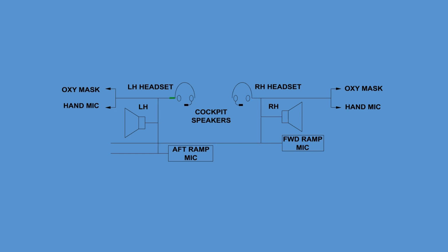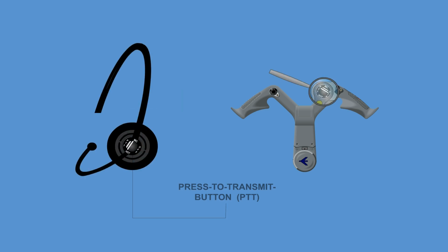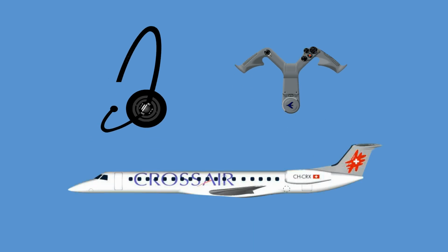The digital audio panel supplies two-way interface between audio signals from cockpit or ground stations or via interphone link. When selected, the press to transmit button PTT on the control yoke and the ground headset to hot mic permits communication directly between cockpit and ground stations.